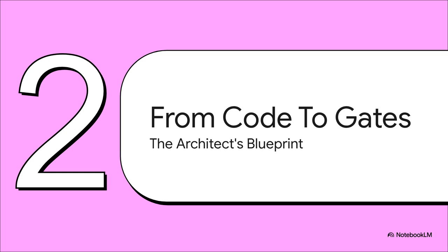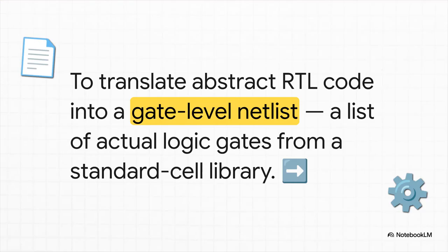This is the moment where the soul of the chip, the code that describes what it's supposed to do, actually starts to take on a physical form. This very first step is called logic synthesis, and its entire job is translation. Basically, a super smart piece of software reads all that human-written code and converts it into what's called a netlist.